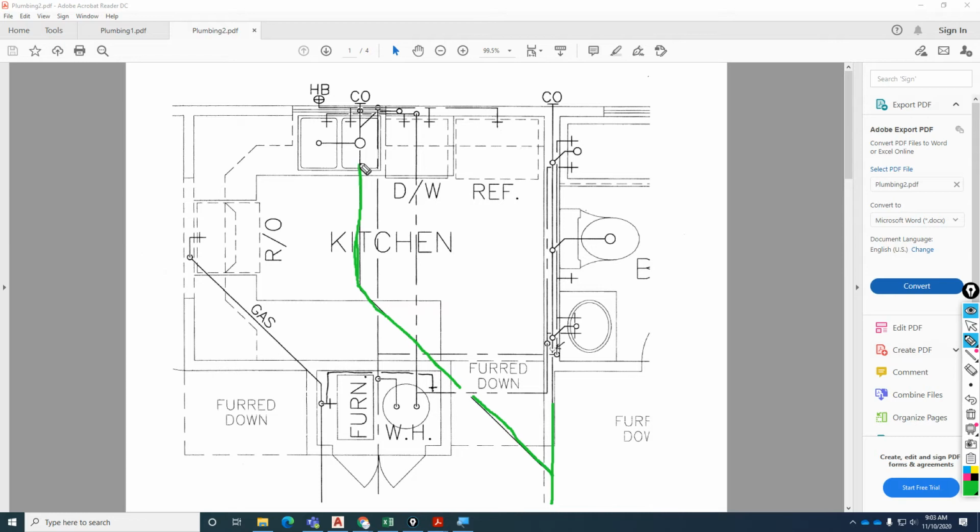We're going to come up with a sewer line. It's going to connect to the garbage disposal in the kitchen. And then the secondary, since this is a double sink, going to continue at a 45-degree angle. We are going to provide a drain for the dishwasher. So the dishwasher, when it washes the plates, uses hot water and cold water. Once it's done with the dirty water, it needs to pump it back out into the sewer system and out into the sewer system on the front of the street.